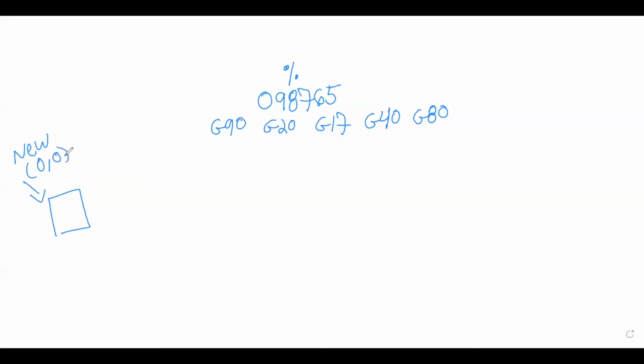So there are 6 work coordinate offsets that can be used, G54 through G59. Now we're going to be using G54 for our programs, and that's going to go on our third line of our program. G54. This is our work coordinate system.